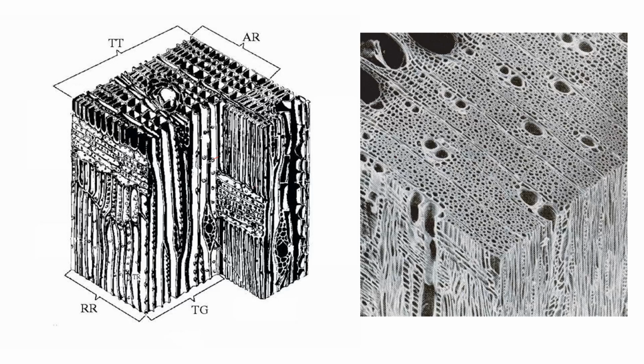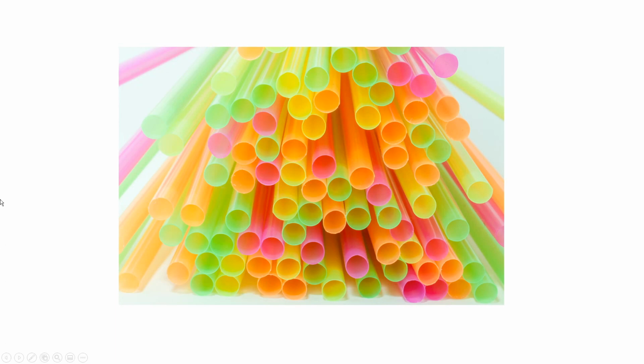And because the cell walls are positioned longitudinally, and the cell walls are what provide a great deal of the strength in the material, you end up with a great deal of longitudinal strength. I always found it really interesting that this is what trees look like at the microstructure level. In effect, you can think of a tree as a bundle of straws, and that's a metaphor we're going to come back to again and again in this course. If you want to think of the structure of a tree, imagine a large bundle of straws bonded together. Taking this analogy further, these straws, the direction of them, is what gives the distinctive wood grain patterns we see in lumber.